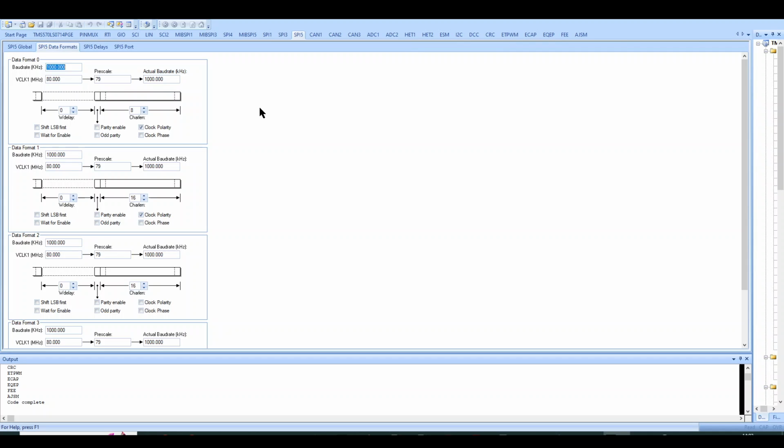You've got to split this 8-bit data into 16-bit memory addresses, or into 16-bit memory address data, but only the lower 8 bits. So it kind of prevents you doing things like a mem copy of, say, a structure straight into your transmit buffer, for example. However, you can work around that. I've made a small API function that does that copying that I'm talking about, but it would have been nice if perhaps they could have created different APIs for each of these data formats, and then data format 0 could have taken an 8-bit pointer. It would have been helpful.